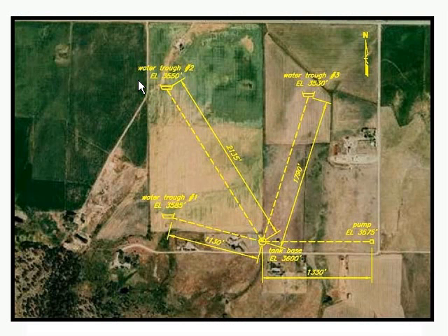You would design a system for basically the worst case of your multiple troughs, the longest distance or the one that's got the most elevation change. You may have to check the multiple troughs to see which one is going to set your design, but you would do it for the worst case design.